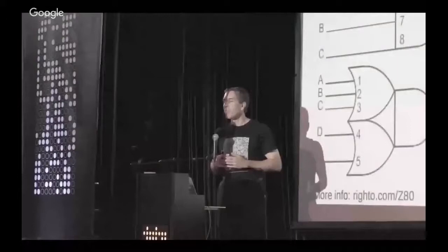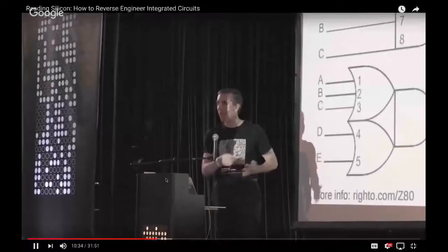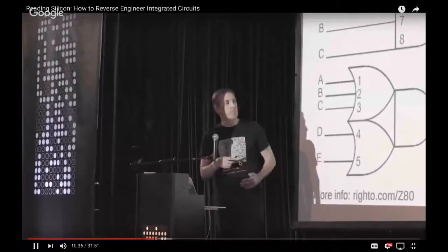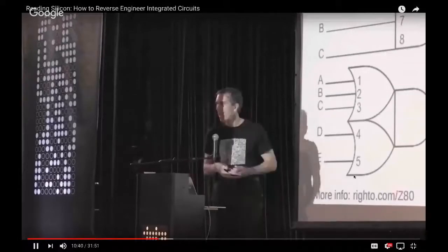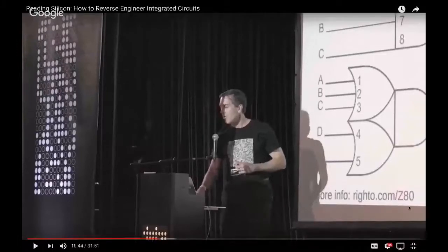So ALUs are really interesting because every chip does things differently. You might think you just take an adder, you take AND gates, and you get the logic you want, but it's all highly optimized. Because it's repeated 4 or 8 times, they try to squeeze out every bit of circuitry they can. The 6502 does things totally differently. So I've written more information on the Z80 and ALUs if you want that there. So that's the Z80.